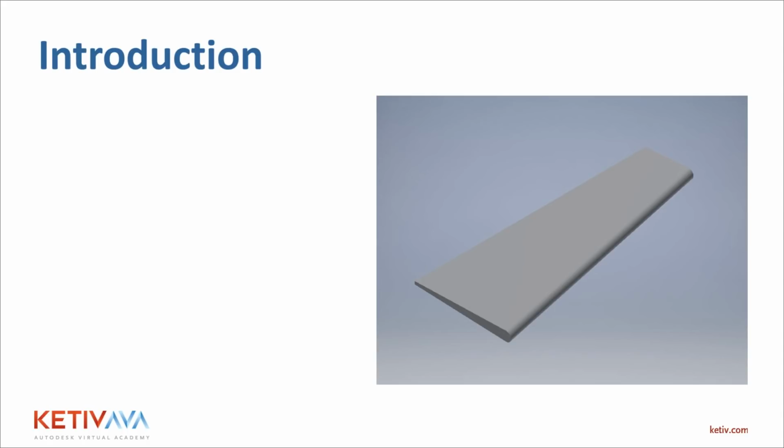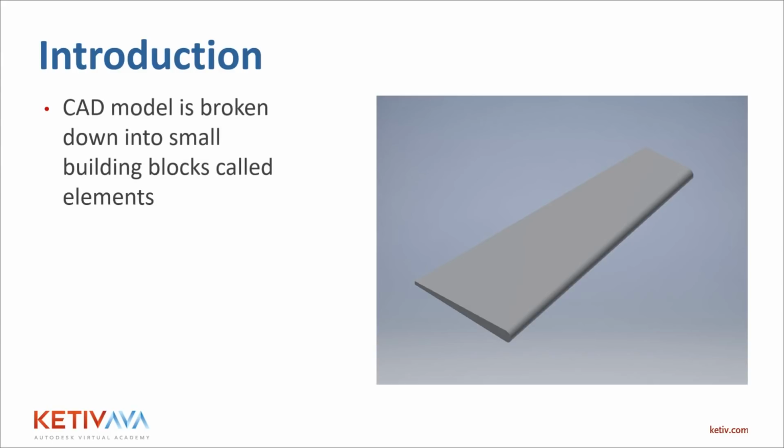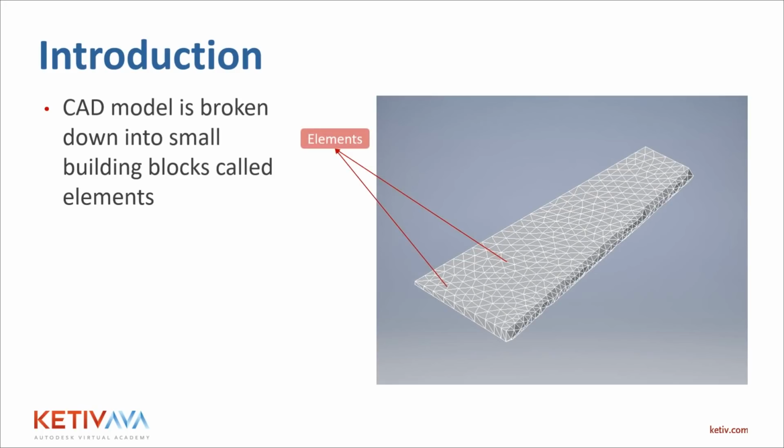Now, in order to compute displacements and stresses and strains, or any other results that may be of interest, the finite element analysis process can be used to obtain these desired results. The process begins by breaking down your CAD model into small building blocks, into a series of finite elements. And these, as you can see here, are the elements. Nastran In-CAD is going to take this CAD geometry and create a mesh for you. A mesh is just an interlocking of these elements.